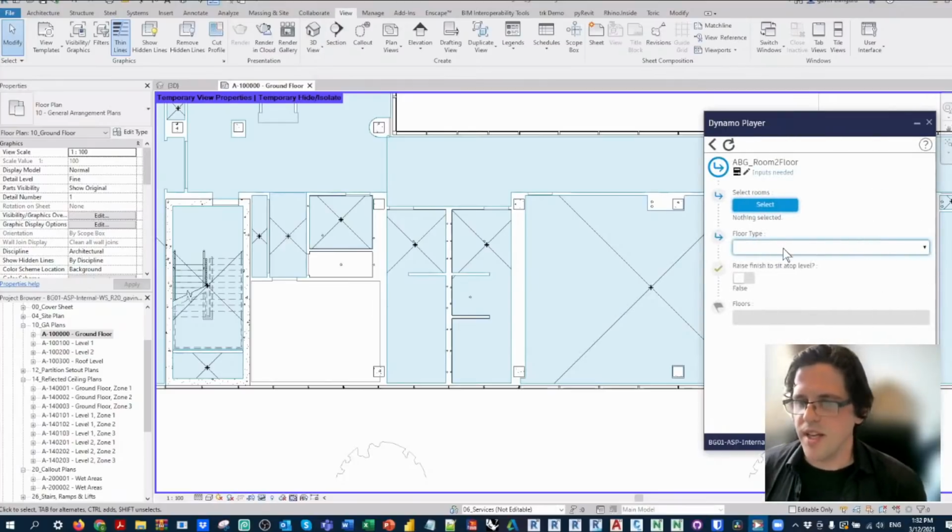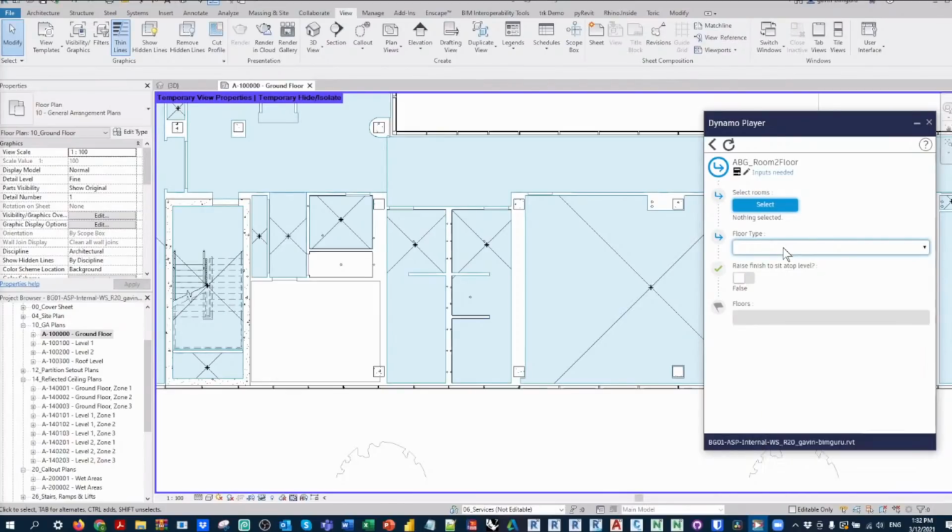Usually I recommend leaving your inputs empty when you build a script for Dynamo Player, because it'll force the user into the inputs mode rather than trying to run the script if something is missing. Whereas a lot of scripts people build might have predefined things that shouldn't be there, and then it tries to run if someone hits play.